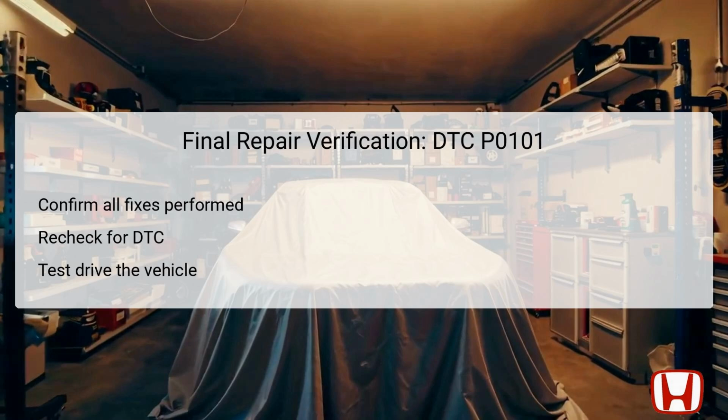Following the troubleshooting steps, it's pivotal to execute a final repair verification. Ensure that all identified fixes have been carried out effectively, whether it involved replacing the MAF sensor or repairing any damaged parts. Next, conduct a scan for DTCs to confirm that no codes, including P0101, reappear.